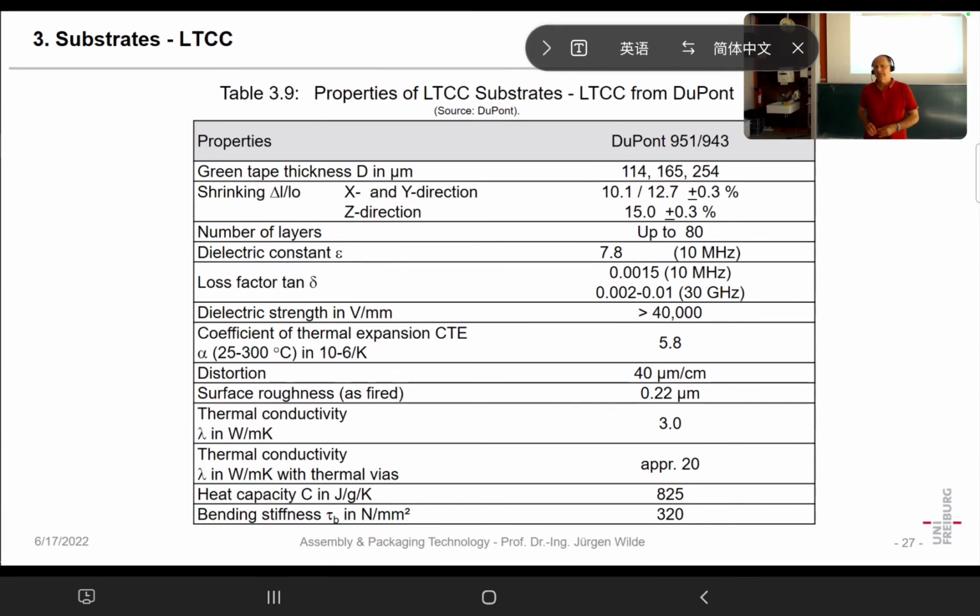We had said it's around 20, 25. Yeah. So a factor of 10 roughly worse. Printed wiring board, a normal quality has 0.2. Yeah, that's still worse. But there can be tricks. What's the thermal conductivity of silver? It's 400.